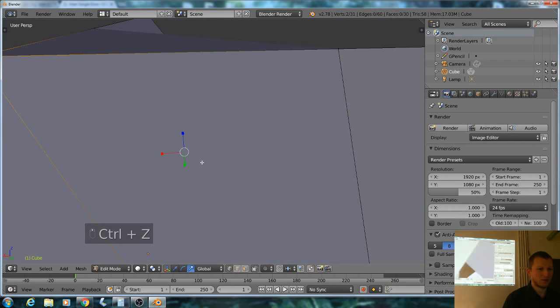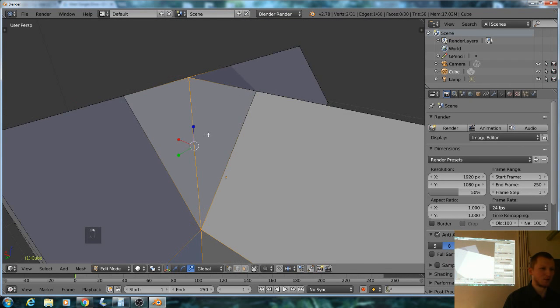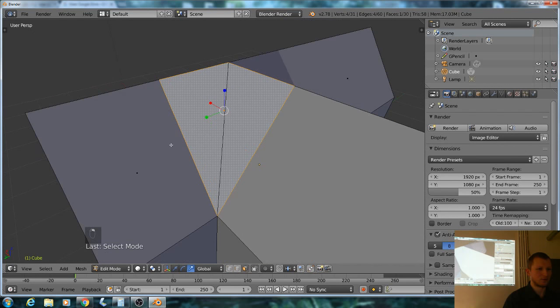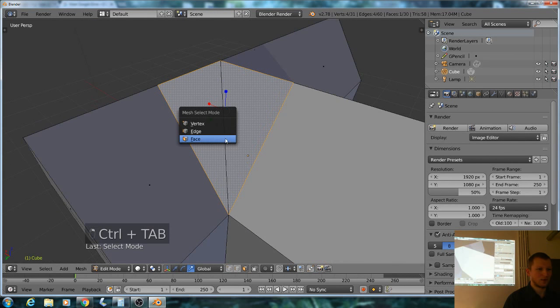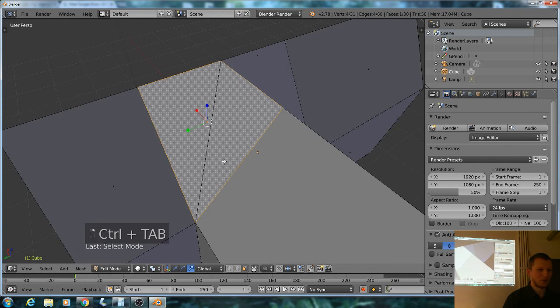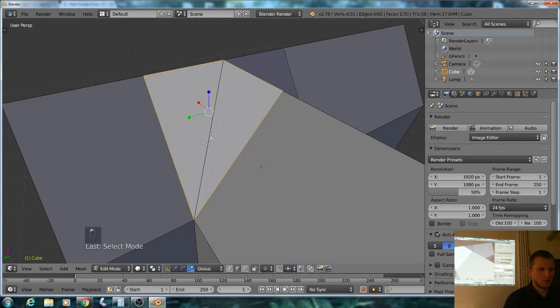So basically, even if it looks like it's working on this side, it really isn't, because if we select the face, then we can still see only one face and an entirely new edge. So this is also a really bad thing to do, also a very common thing people do, that there is some geometry still laid on top of each other, but you don't really need it.